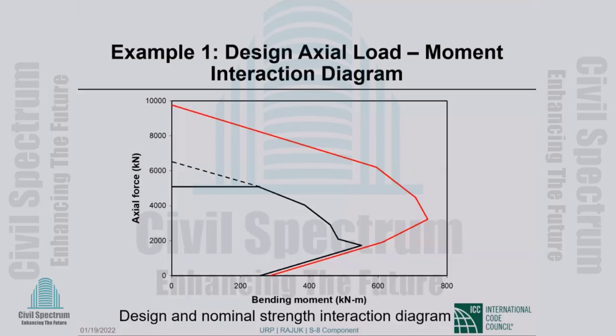You already discussed this. That's what I was saying. Every lecture you discussed at the beginning that the bar has to be laterally supported, and if you have more than 6-inch clear spacing, then additional lateral support may be needed.